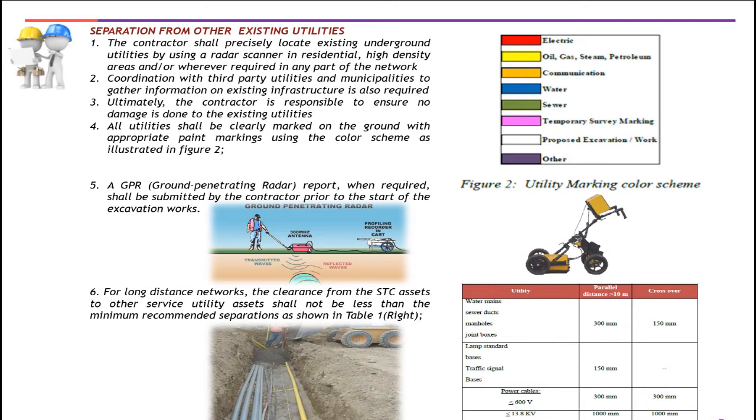And for other utilities like lamp standard bases and traffic signals, make sure that the separation between STC assets and these utilities will be 150 millimeter. For power cables or electric cables, we'll have these different parallel distances.